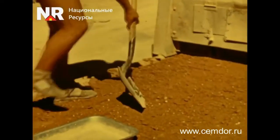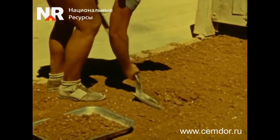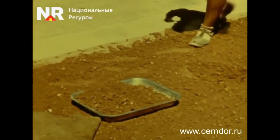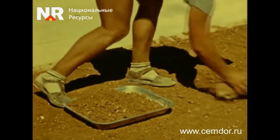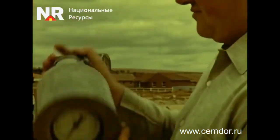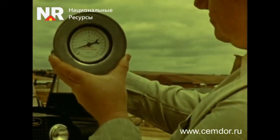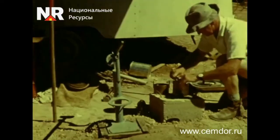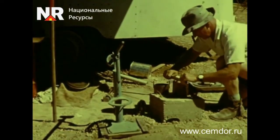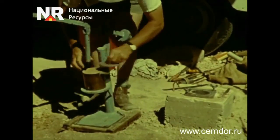Samples of the mixture are collected immediately after the mixing machine passes. They are used to determine the optimal amount of water in the mixture to ensure maximum density. The exact amount is carefully measured and determined, using specialized equipment. The design strength of the soil cement is determined by studying the strength characteristics of soil samples molded from the laid mixture at the site and tested at the design age.